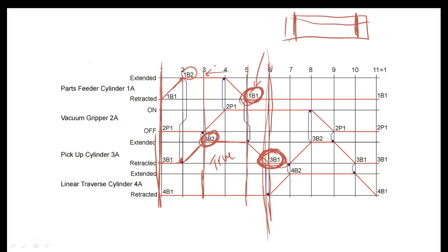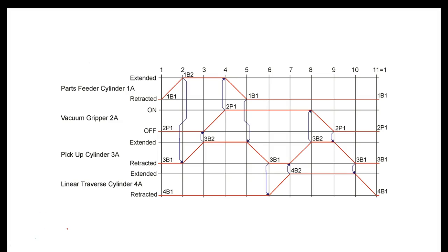Well, the reason I was asking, we had a situation last week where the conveyor lines have rock sensors. The metal pallets carry the engines, and it's got rock sensors in between the rotors on the conveyor. That rock sensor has to see metal, and when it senses metal, it stops.